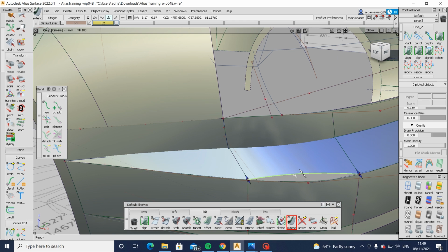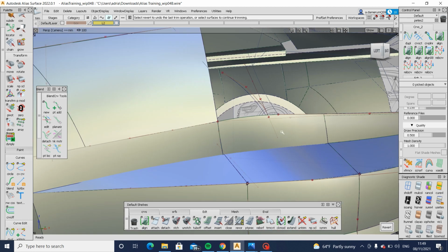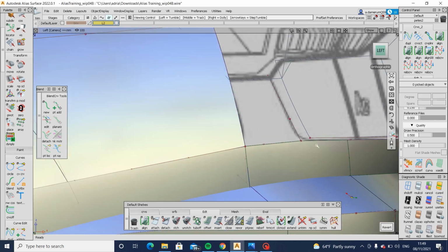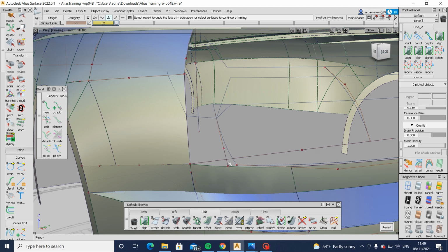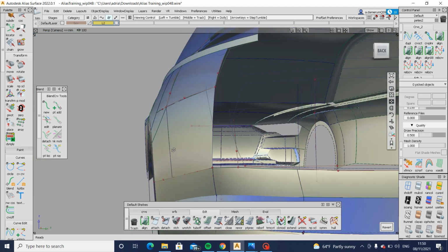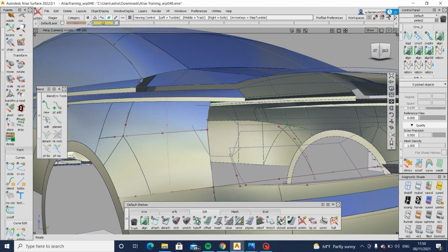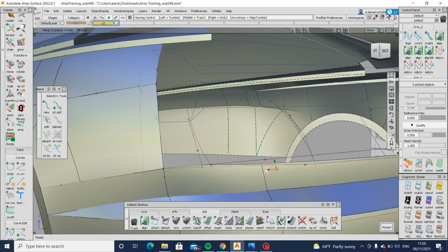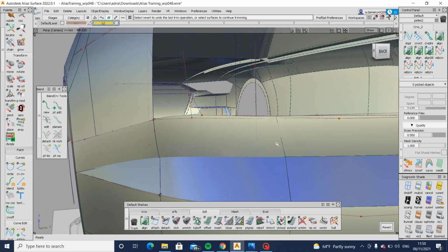Edit, extend, trim that back. Okay, and do what I did before where I projected on the core lines. Just trim that back. There'll be a surface up there now that will build, but like I said before, it's almost like there was a core and there was a blend round and then it was trimmed away. So I mean, we can try that. So let's trim that back.